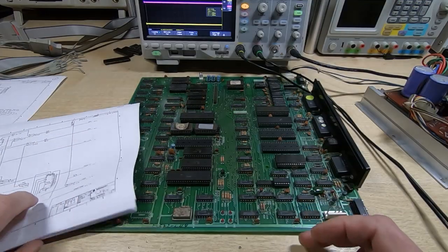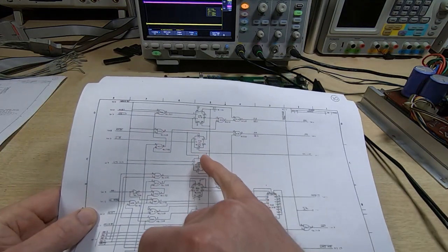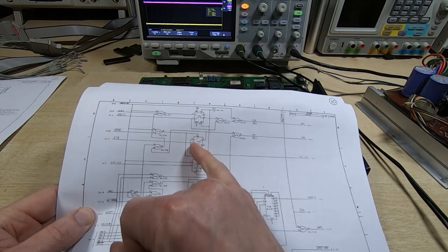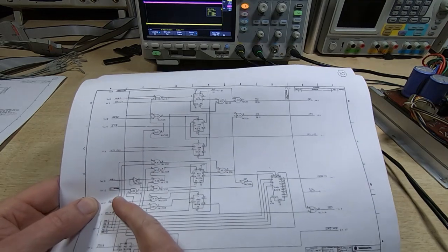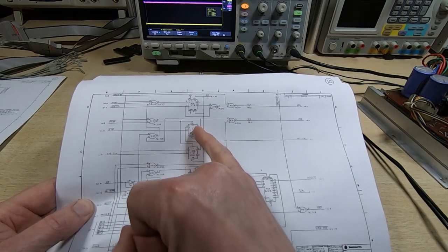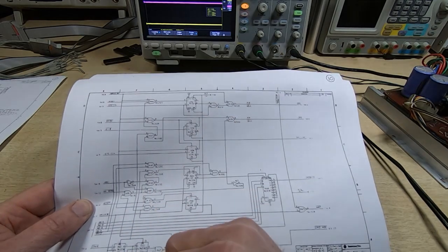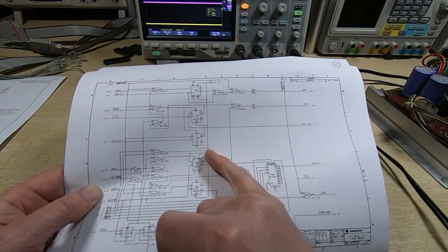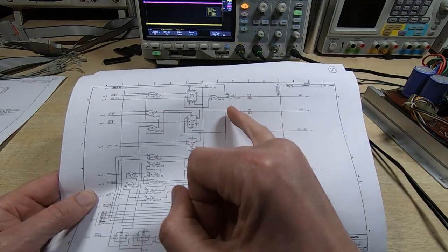Okay, well, it didn't take long to locate the fault. One of these 7474s was not doing its thing, and that was pretty much in the path that we expected. So we've got the CAS signal coming out here, and despite getting the proper clock and also getting the proper request for DRAM, this flip-flop was not doing anything. There was no output. It was always staying low, which meant that this was never being enabled, and so the CAS signal wasn't getting to where it should do. We were getting the proper strobe signal coming through, so the timing was correct. It's just the gating for the CAS wasn't working.